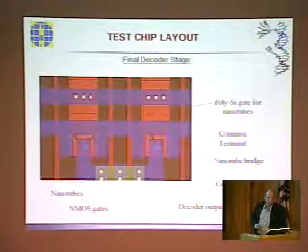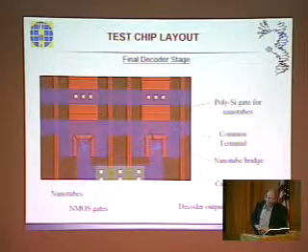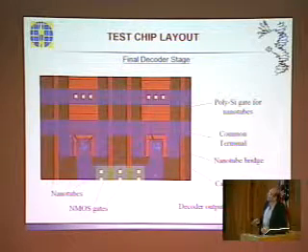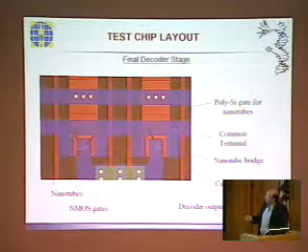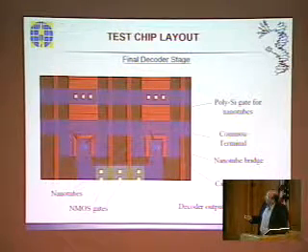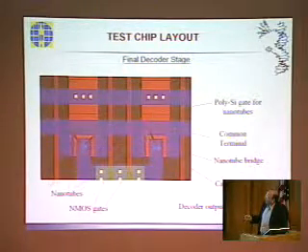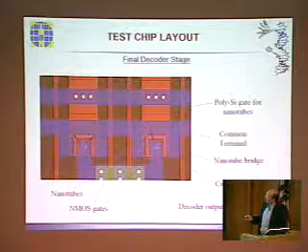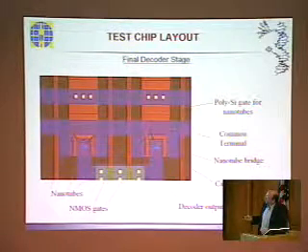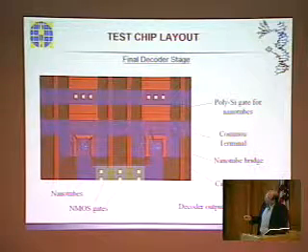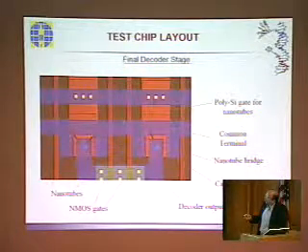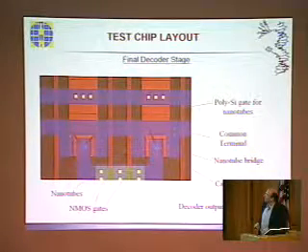Okay, this just shows a blow up of the layout of the business side of the layout, where we have the last terminal of that tree. The red gap here is essentially an oxide film with polysilicon gate underneath it to act as a gate for a carbon nanotube that is catalyzed to grow from this point and span across this gap and connect to the interconnect metal on the other side here.